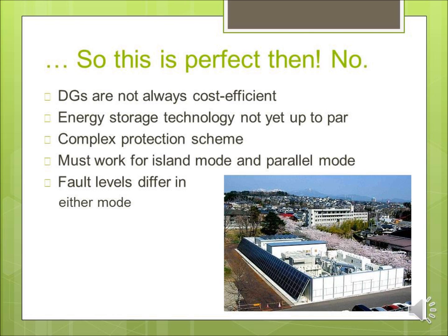However, there are issues. Distributed generation is not always cost efficient. Energy storage is also not up to par. This is particularly an issue because intermittent sources like wind and solar power are unreliable. There are also a number of complexities when dealing with faults in the microgrid.